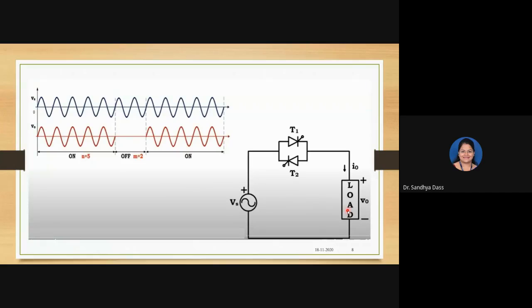In such a way, what will happen? We can have as many cycles of output as required. So in this case, say here n is equal to 5. Depending on the average output required at the load, we can decide the number of cycles for which I want to keep the circuit complete so that I will be getting an AC signal at the load, right?